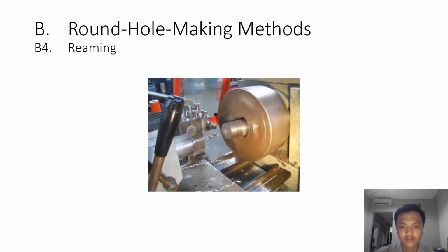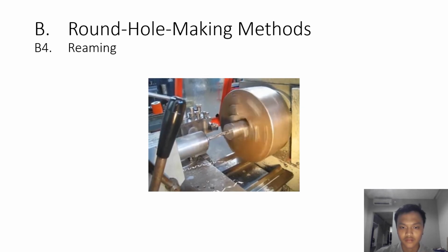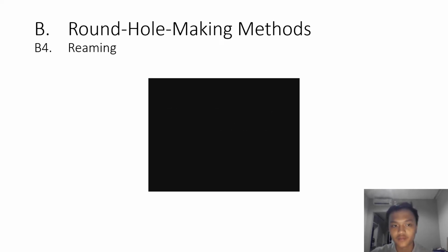Calculate and set the reaming speed according to the reamer size. In this case, a 12mm reamer is used at approximately 500 RPM. Swarf should be kept clear to prevent the machined surface from scoring. Now that is the reaming operation.